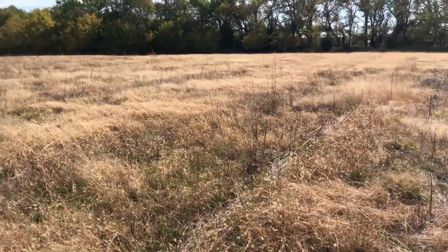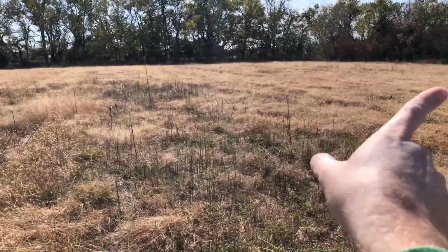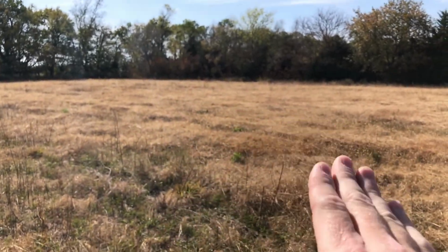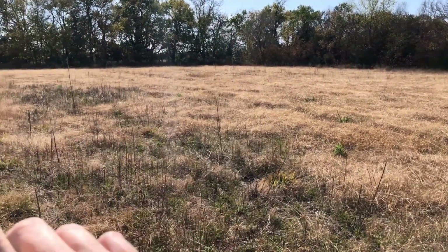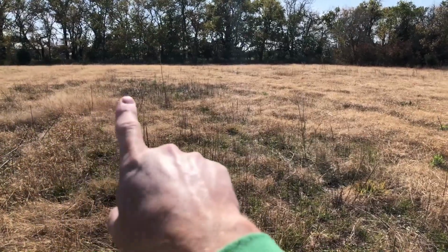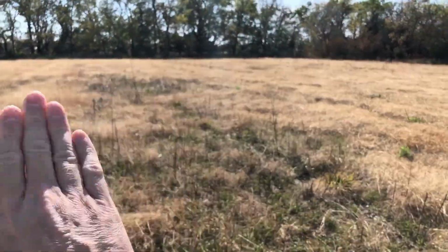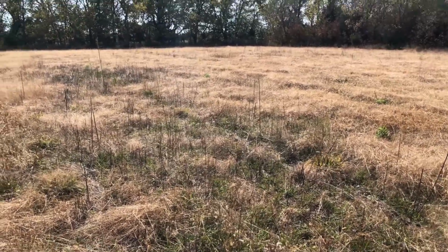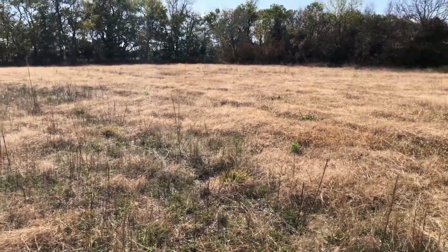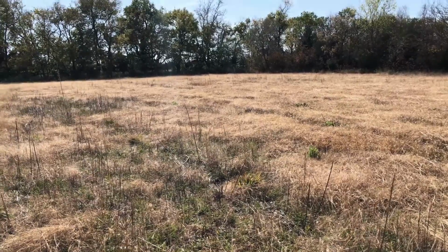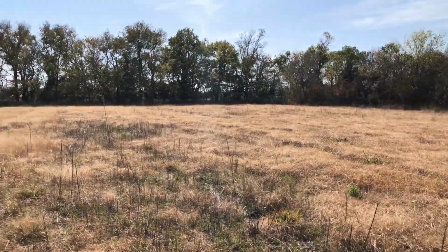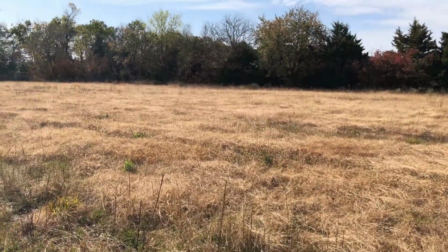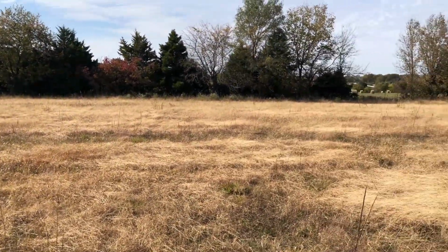So we kind of are going to be facing that direction, south-west. So we're going to be facing more west than south, but trying to orient the house so that the south-facing is going to be the garage, laundry, master bath, master closet. So those are uninhabited spaces, so I don't have to worry too much about heat. But I'm going to do my best to insulate that wall really well. So I'm trying to orient this house to help with energy, but that's pretty much it for out here.